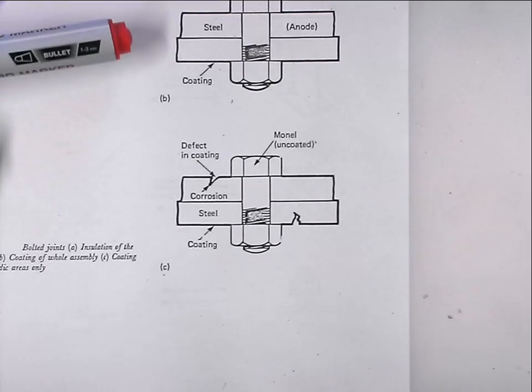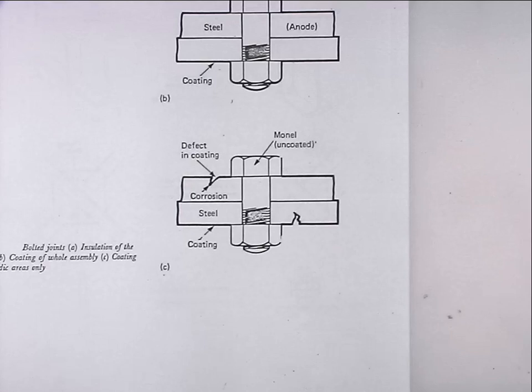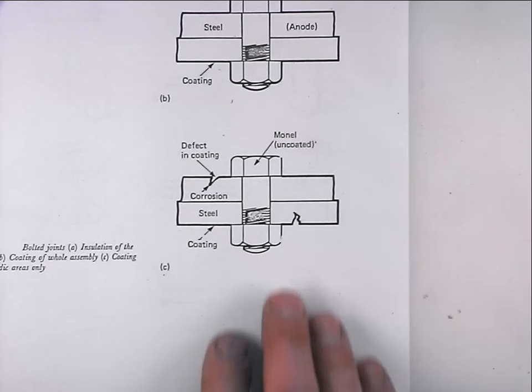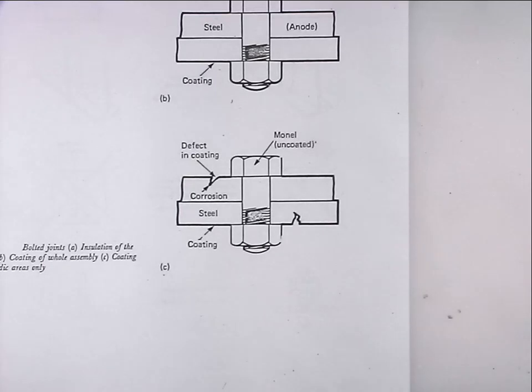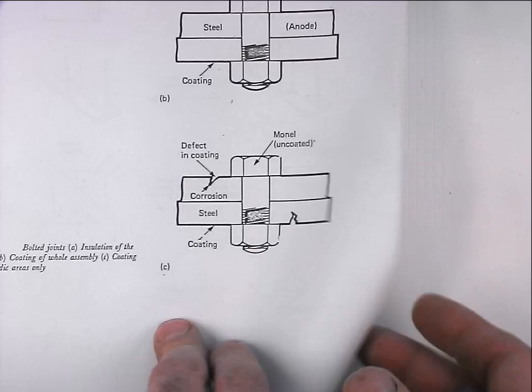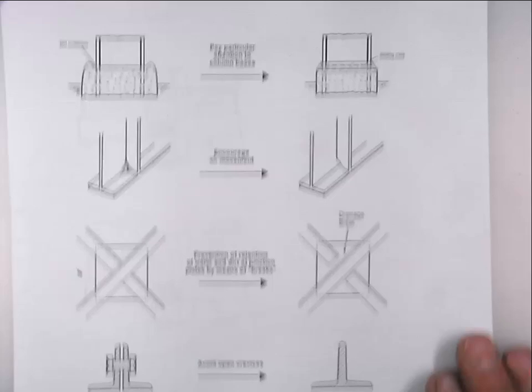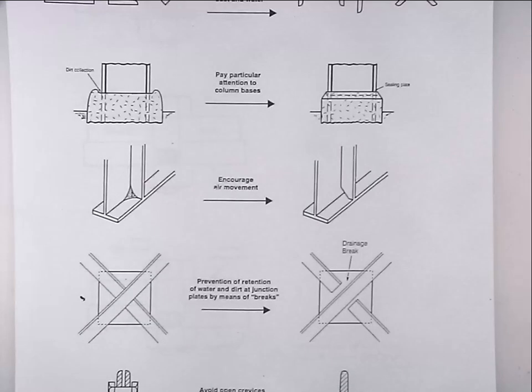The other options are simply design options about drying out the environment. These particular ones are from a civil engineering situation, but the same general policy is true for other applications. What you don't want is little pools or reservoirs of solution left lying around your components, whether it's a chemical plant or a pumping station or whatever.